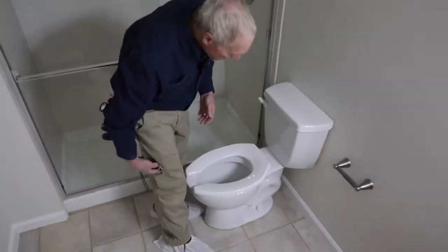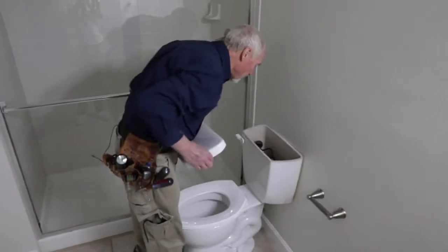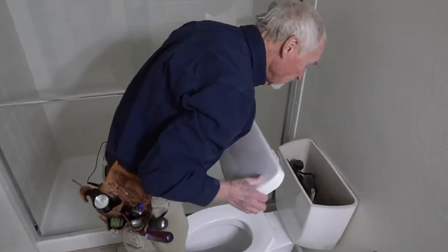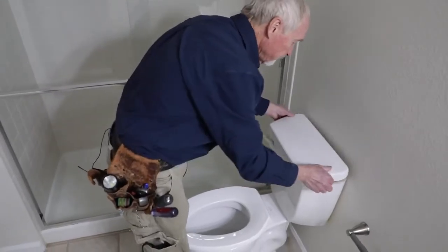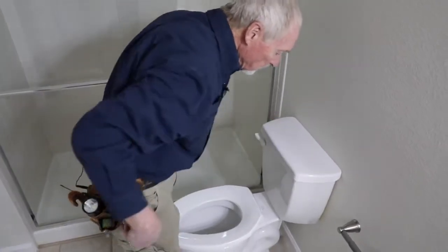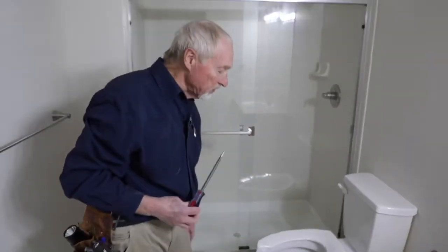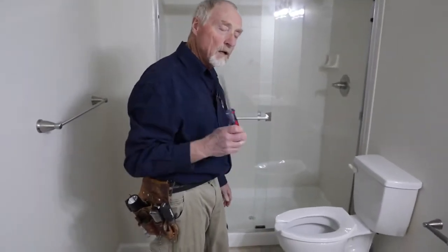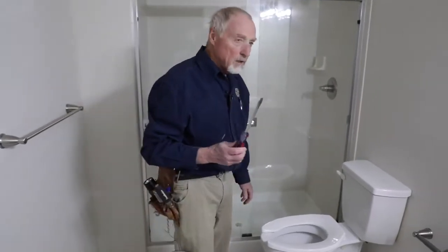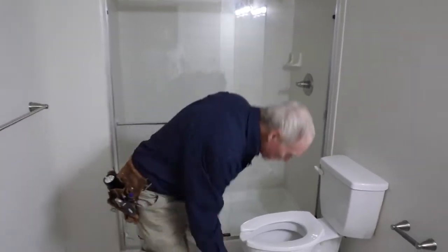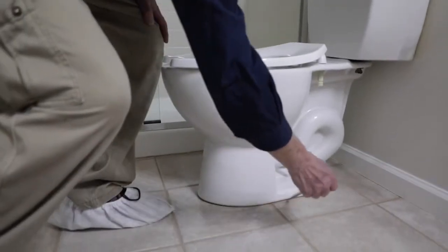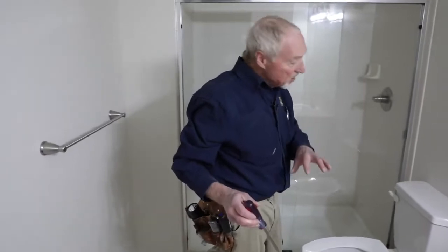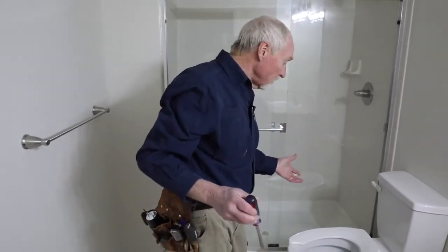And then, always worth a quick check on the inside, see if there's something funny going on there. This one is actually very clean. One thing, toilets are supposed to be sealed to the floor, and by the way, that means sealed completely around the base. An easy way to check that is take my screwdriver and go around the edge. I don't have any caulking there. Oops, that's a mistake. We would recommend sealing.